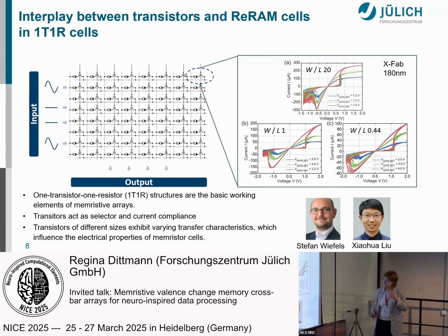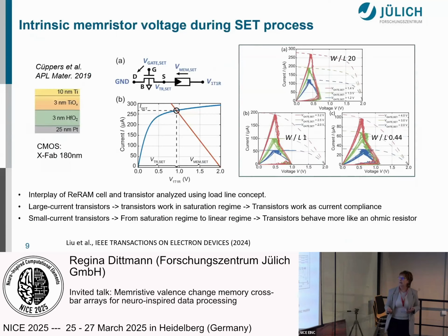But as you can see here, the size and the dynamics of the transistors have a strong impact on the electrical properties of the memristor. Therefore, we spent efforts in investigating transistors of different sizes and looking at the distribution of the voltages and the dynamics of the system depending on the size of the transistor.